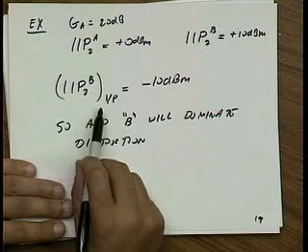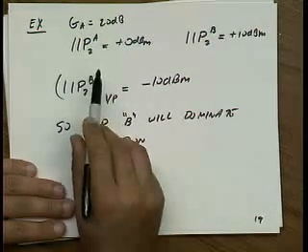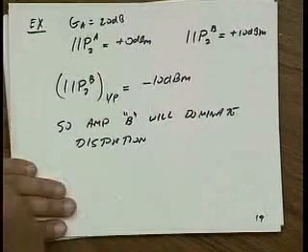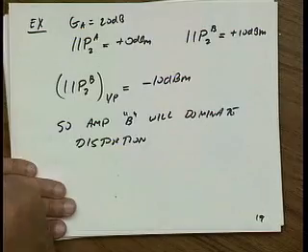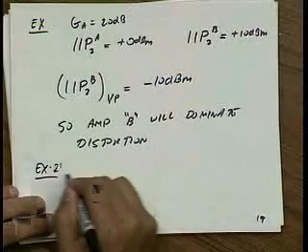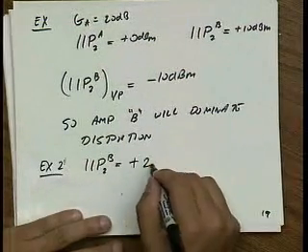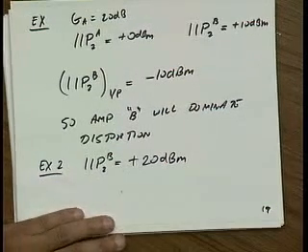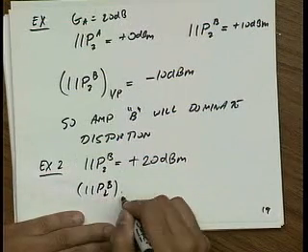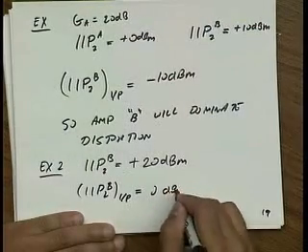If on the other hand this input IP2 point is close to this point, then I use the law that they're in parallel. So the overall IP2 is worse than the IP2 of either one, right? So if they're both equal, let's take another example. Let's say I use the same first amplifier, but now I go out and buy a more expensive amplifier that has a 20 dBm input IP2. Now if I input refer that, that's 20 dB minus 20 dB, so it's 0 dBm.